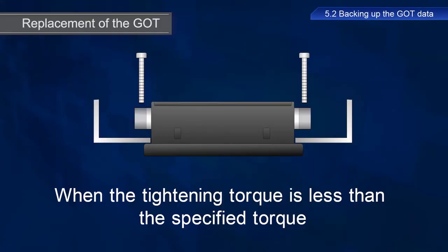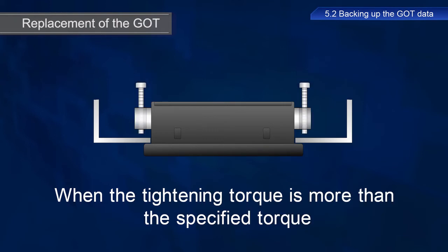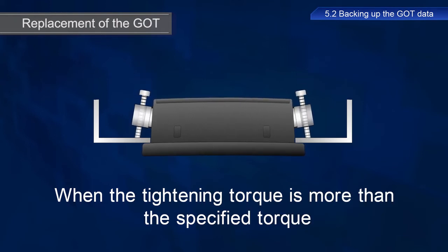If the tightening torque is less than the specified torque, the packing will not form a proper seal and allow water and dust to contaminate the device. Conversely, using too much tightening torque could result in operation failure due to panel deformation or damage, or cause some other failure.